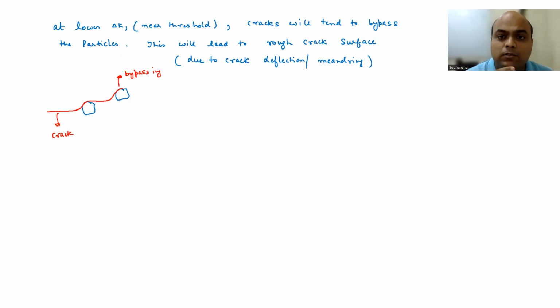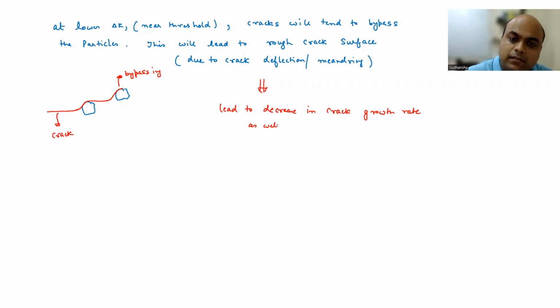So it is going to decrease the crack growth rate, isn't it? Because the crack length now becomes much larger. Okay, so when this happens, this leads to decreasing crack growth rate as well as higher delta KTH.